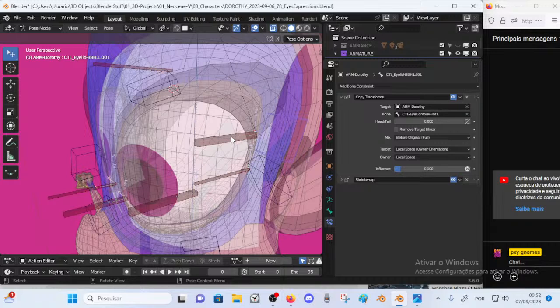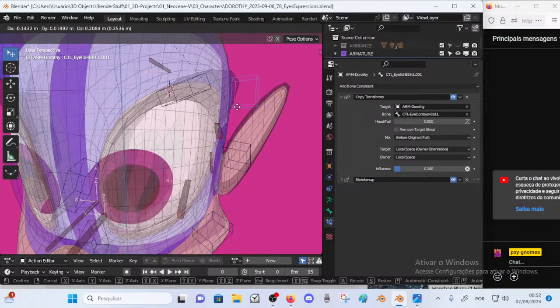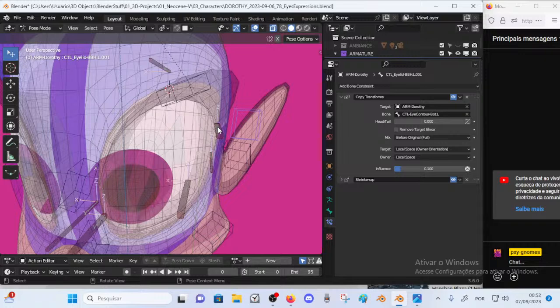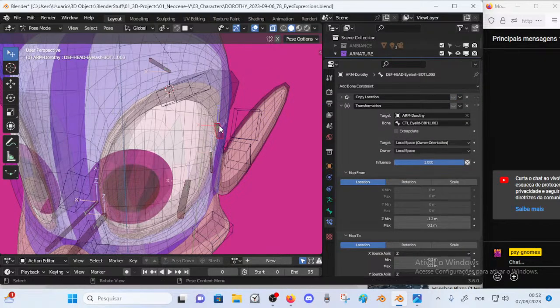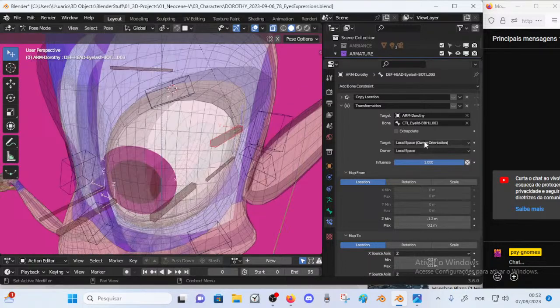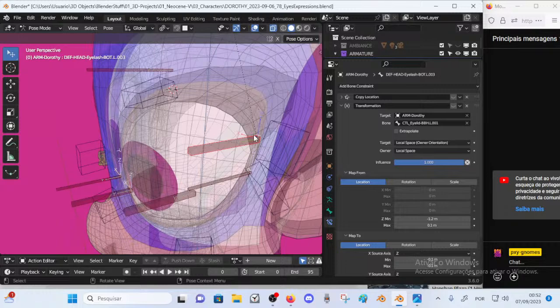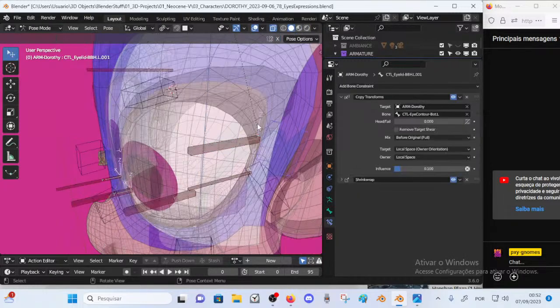this will be using also the owner's local space. So this gizmo here for this bone, as this bone moves, it will be using the space of this bone. So even though I pose it anywhere here, it will be using this data here, and so this means that I can have this align axis and still target the bone, right?